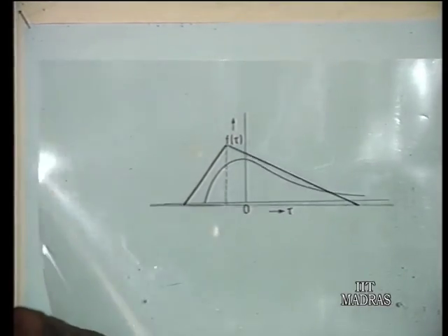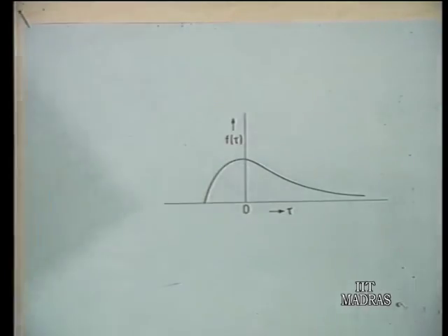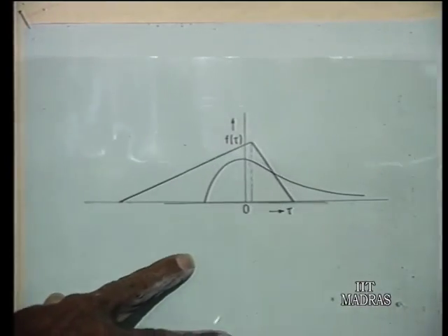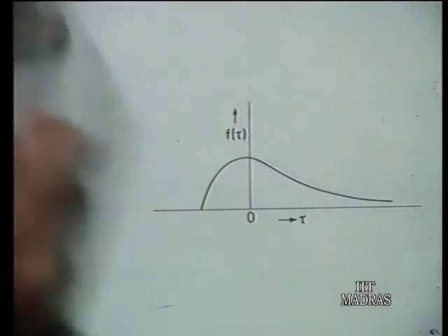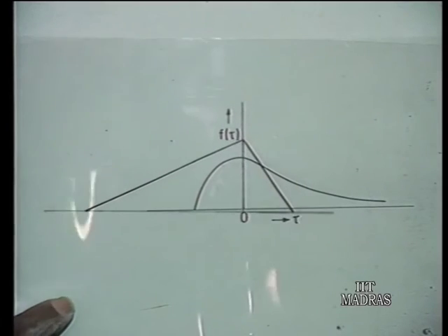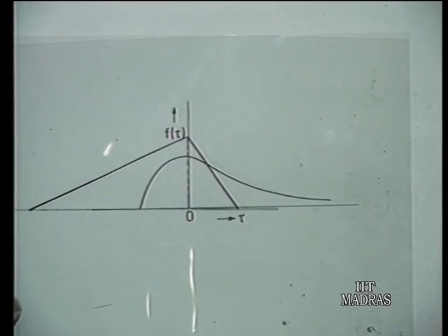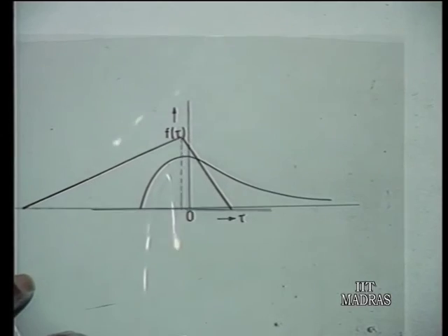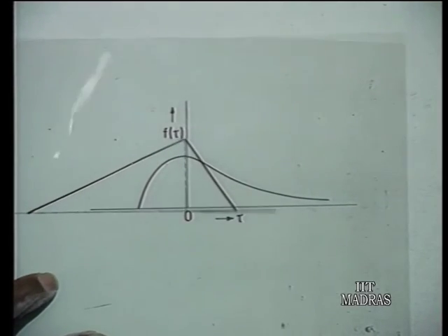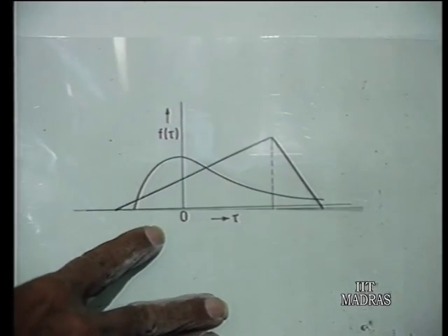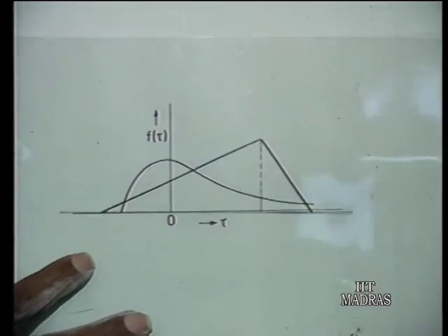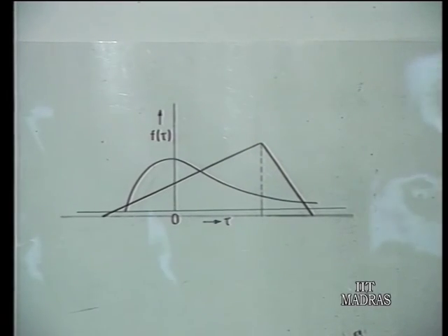So what we are doing now is, instead of having g(t) like this, you fold it like this. So g(t) originally was like this, now you folded it, that means you made this run backwards. This is now g(minus t). Now depending upon the point where you want to find the convolution, you shift it like this. So for various shifts you find out the product of these two curves and find out the area under that curve, and this is how one can calculate the convolution integral values for elementary time functions.